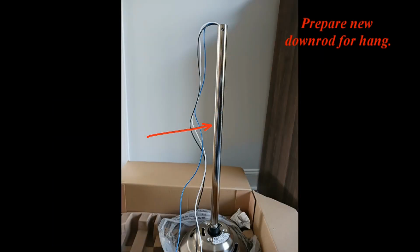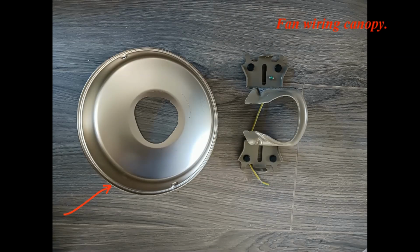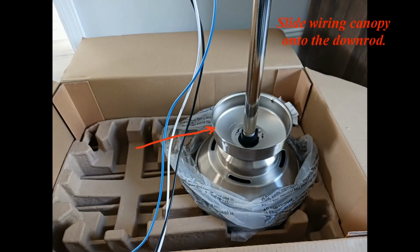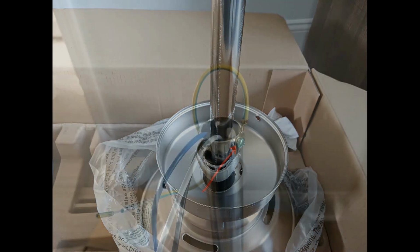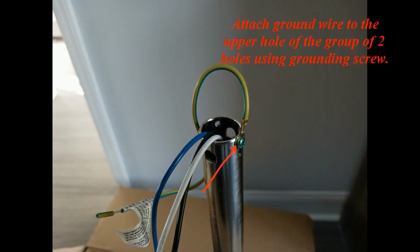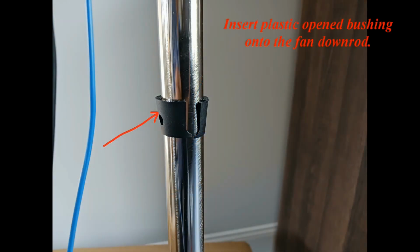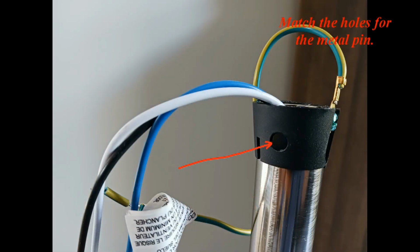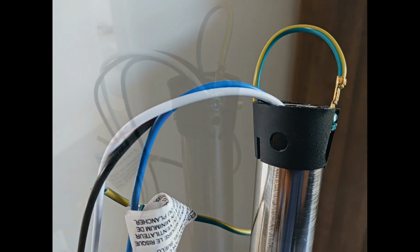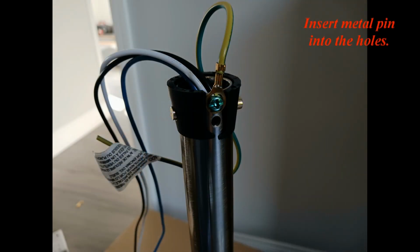Prepare the new downrod for hanging. Fan wiring canopy: slide the wiring canopy onto the downrod. Slide the downrod's hanging ball onto the downrod. Attach the ground wire to the upper hole of the group of 2 holes using the grounding screw. Insert the plastic opened bushing onto the fan downrod. Slide the opened plastic bushing up the downrod. Match the holes for the metal pin. Insert the metal pin into the holes.